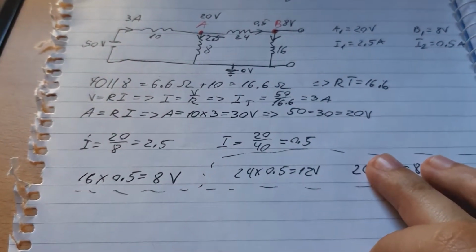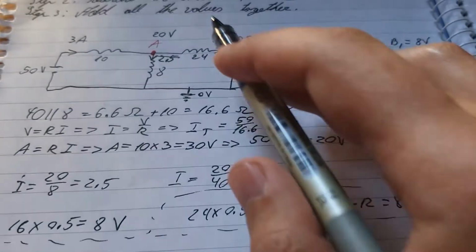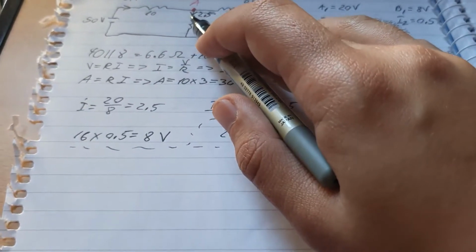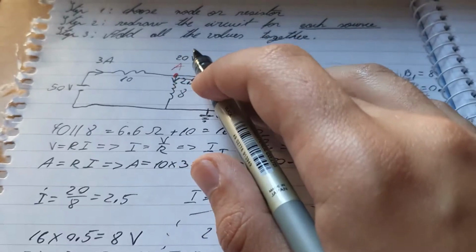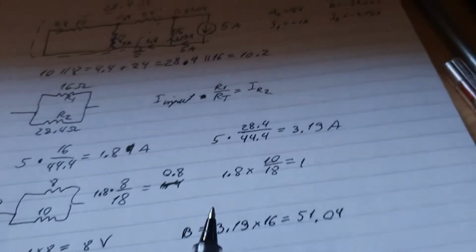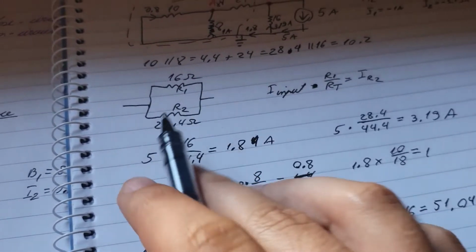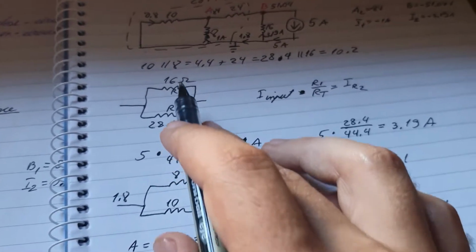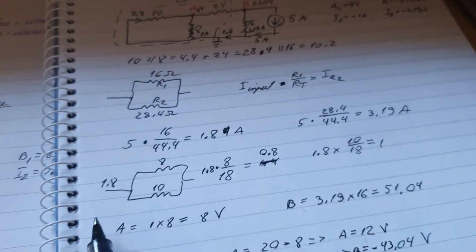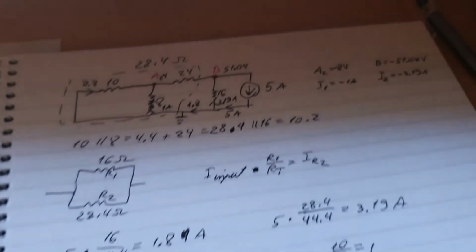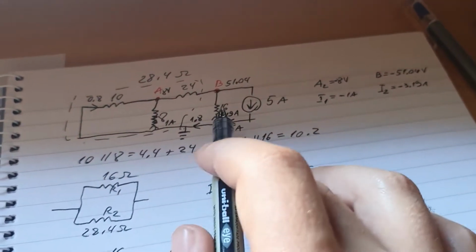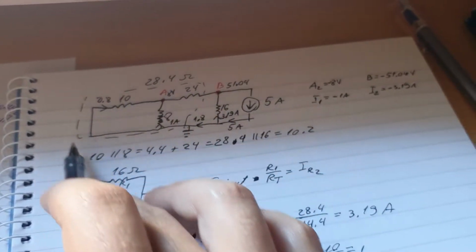Okay, so overall, we learned how to calculate the nodes of the voltages. We also learned 2 methods to calculate the current. First one being using a voltage and a resistor to find out the current. And we also learned how to calculate the current split when having only current sources and resistors. When we don't have a voltage, we apply this formula, this method here. And we also need to make sure that when we calculate this bottom split, we integrate all 3 resistors here.